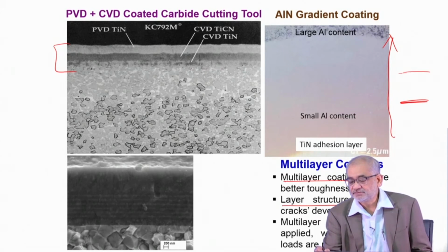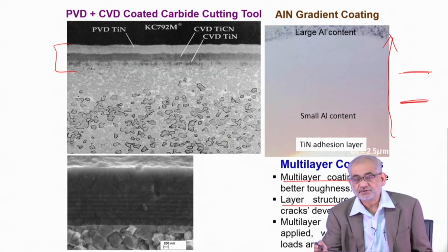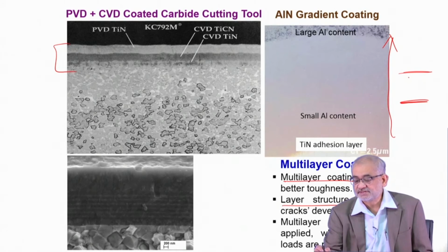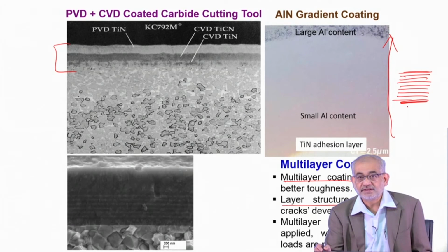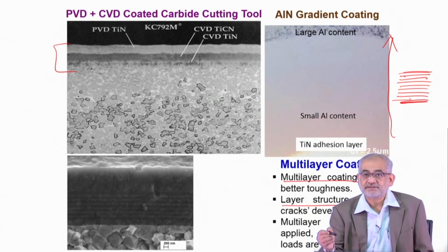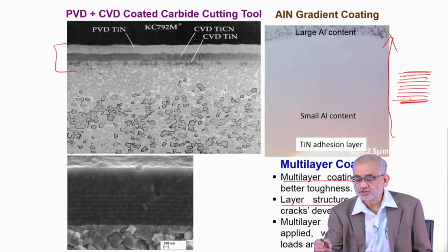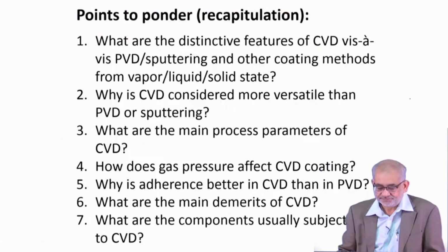But if the same coating, maybe a carbonitride or a mixed nitride or a silicide, is done in alternate very thin layers, then the mismatch is accommodated nicely, and the stress generated at the interfaces is minimized, and as a result you can make a much more adherent, durable, and mechanically stronger coating on top of the substrate.